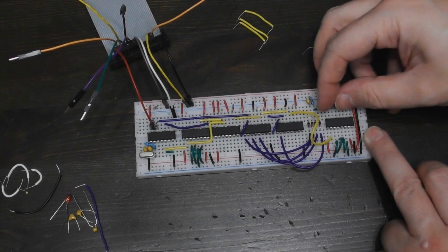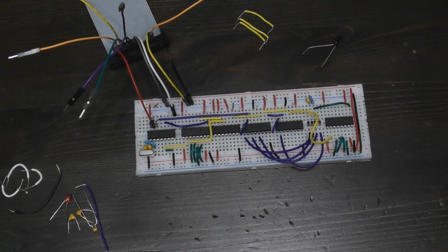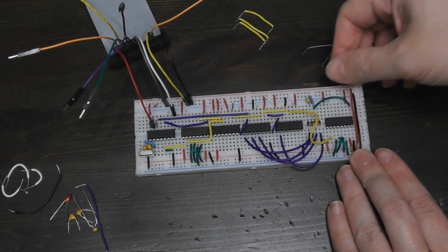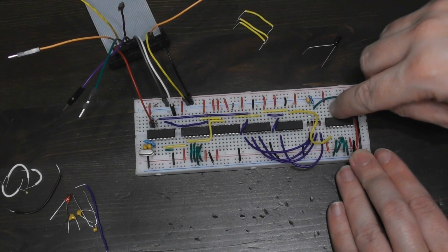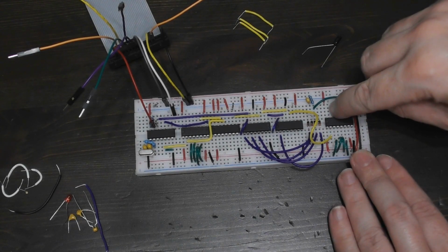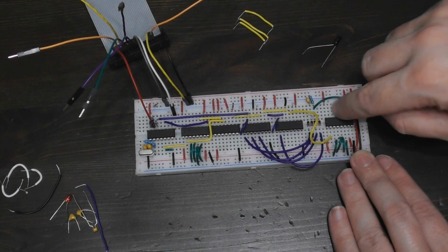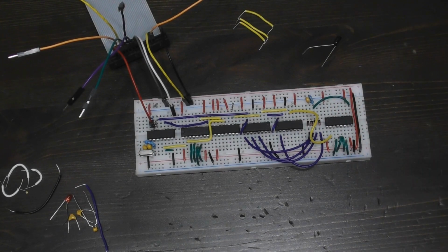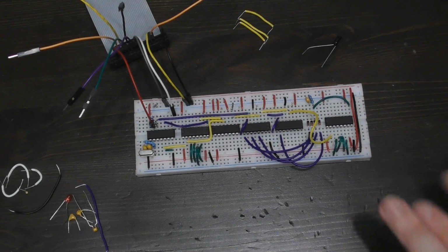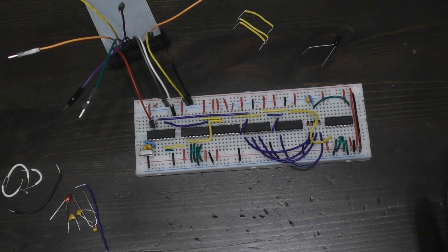Like that. And then the only other thing to hook up here is, I think, pin 15, the carry from the counter, and that's what we're going to use to tell the Arduino when it should take some data. So I'll get that hooked up to the Arduino, and I'll update the code, and I'll run it, and I'll see whether we get a more consistent sector dump this time.